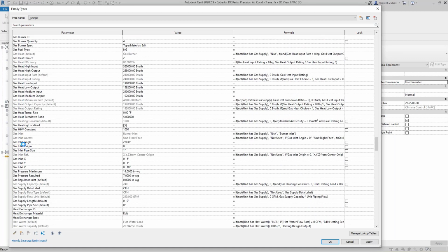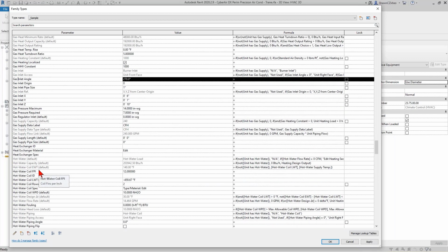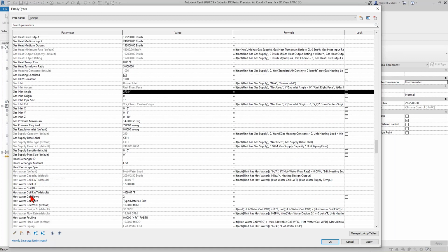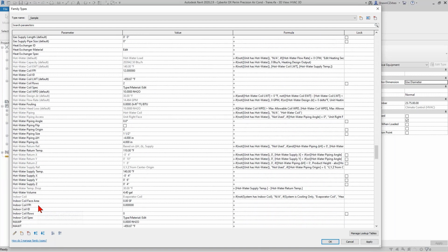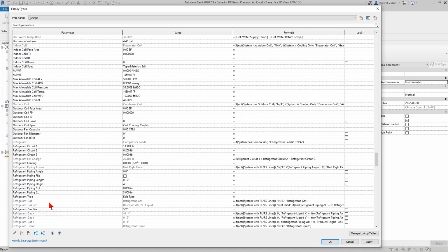Now, normally to get rid of these items, you would select a particular parameter and you would hit delete one by one, select, delete, select, delete, select, delete. And I can do that. It's going to take a minute, but I can do that one by one if I really wanted to. Now, for me, I find a faster way to get rid of this is to use something that lets me batch delete some items. And that's where we're going to dig into the more automatic technique. I'm going to be deleting a lot of these elements, a lot of these items inside of here that I don't need, simply by filtering for these parameters and deleting them, adding them to a deleted list in Family Processor, and just let that rip. And it'll take way less time to get rid of them.